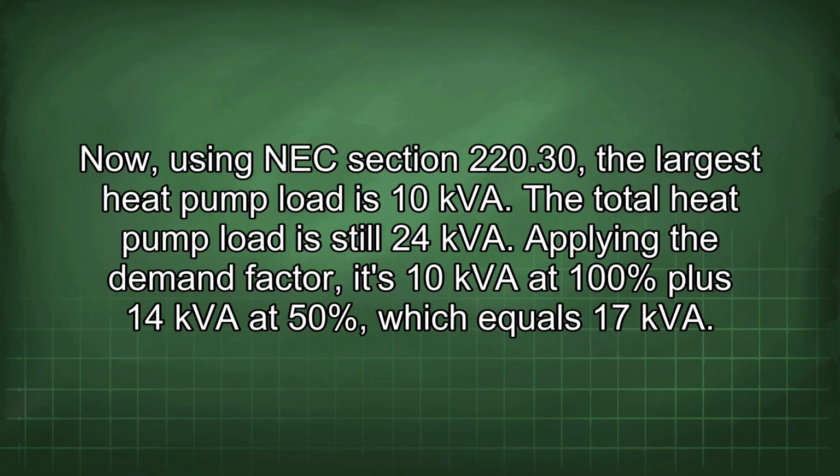Now, using NEC section 220.30, the largest heat pump load is 10 kVA. The total heat pump load is still 24 kVA. Applying the demand factor, it's 10 kVA at 100% plus 14 kVA at 50%, which equals 17 kVA.